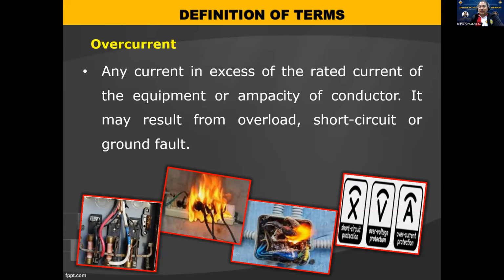With short circuit, the flow of current really changed. Because instead of having that complete circuit from source to load then back to source, it is possible that the load is bypassed, our two lines, line 1 and line 2, are shorted, or shorted to ground. So our flow of current is different now, no?